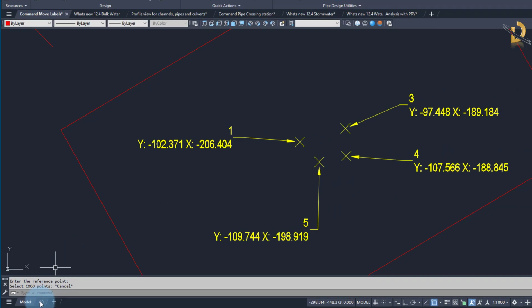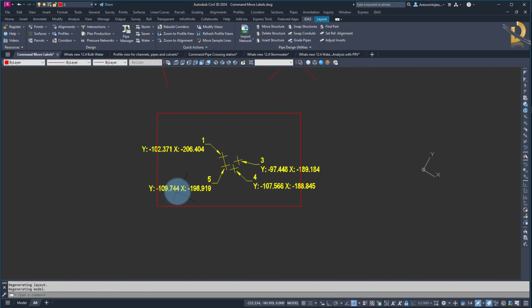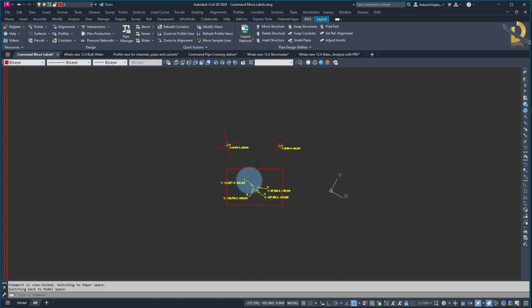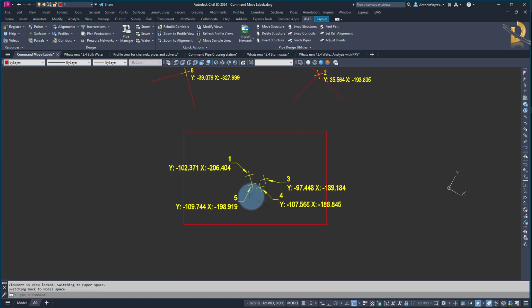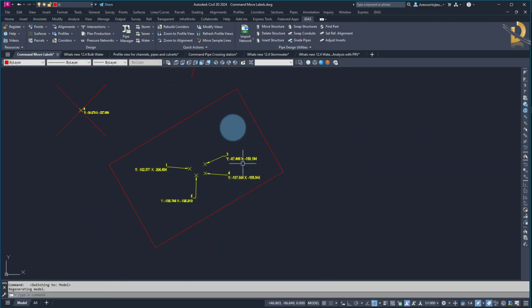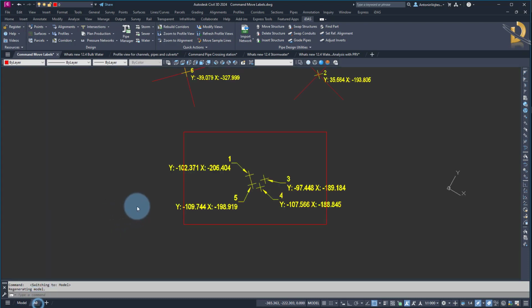If you often work in a paper space, and that's the area you generally work because the important is the outcome on a paper, not how it looks in a model space, then those slopes can be calculated based on the rotation of the drawing. As you can see, that platform, the rectangle, is sloped or rotated in this view, in the world view. But if I go to paper space, the paper space is rotated.